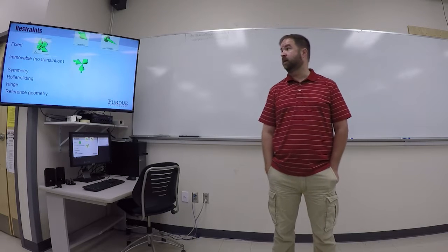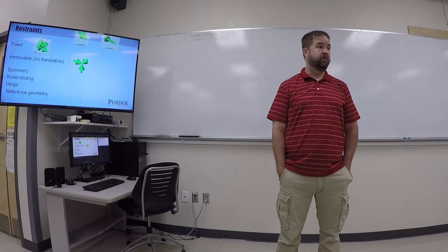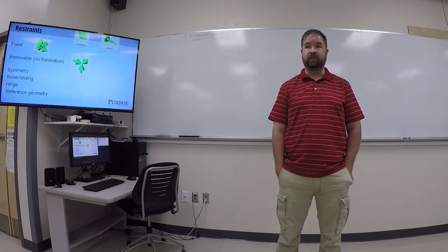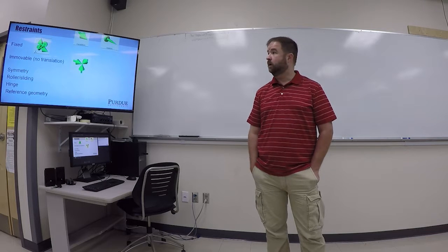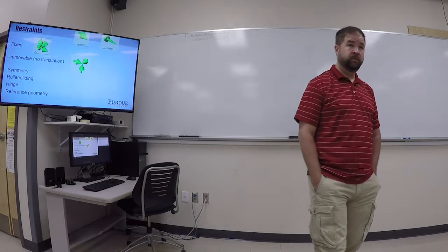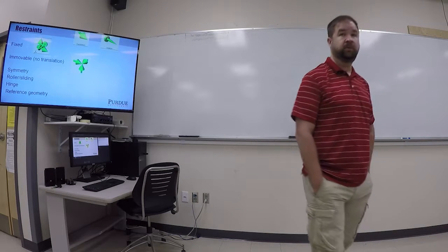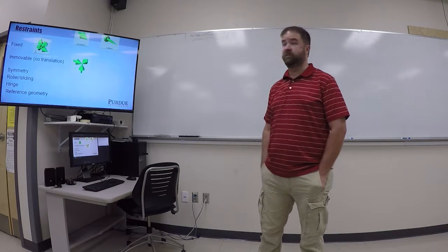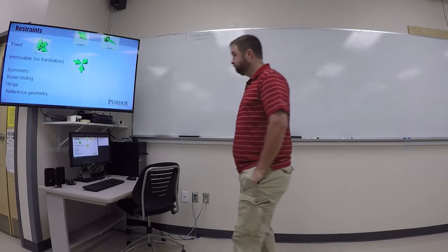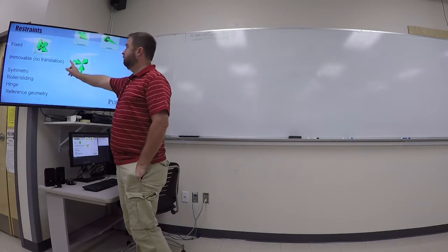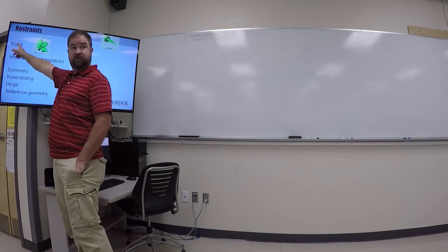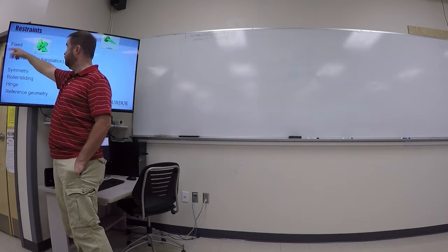Think about a flagpole that is buried into the ground so that it is not able to move in the X, Y, or Z direction, and it's also prevented from rotating in the X, Y, or Z direction. That's a fixed connection. We've talked about those in statics and strength of materials and so forth. This is a standard menu click to create a fixed connection in SolidWorks. You don't have to do anything special.